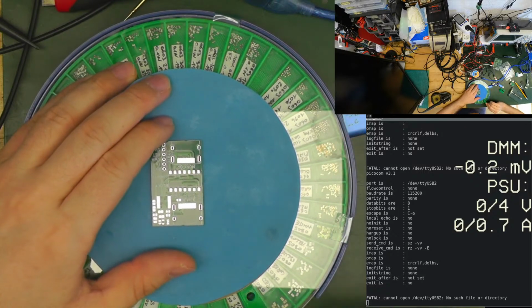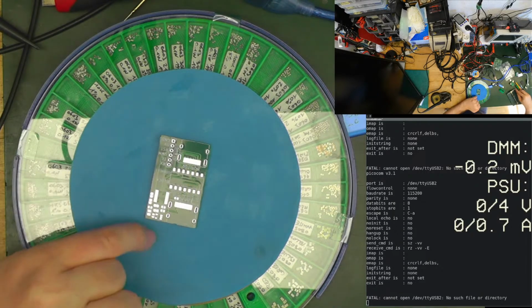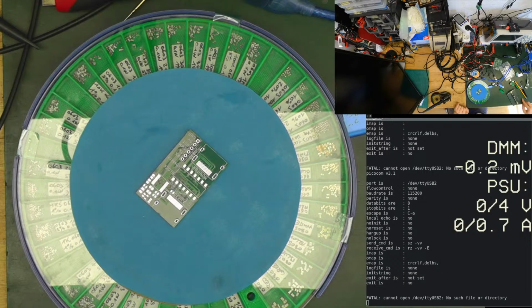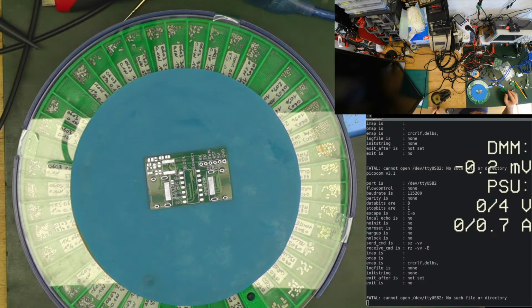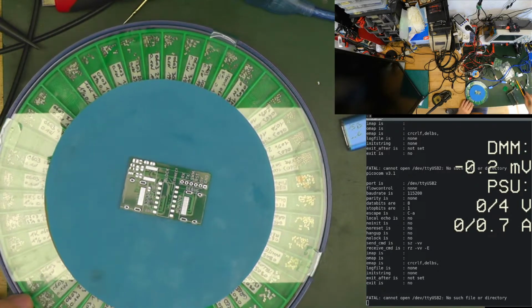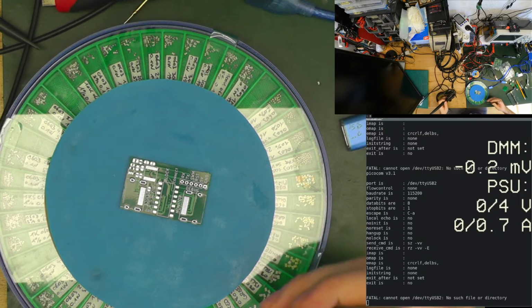Okay, and I will change also the pink LED. And I added, so you probably didn't see it, a footprint for the EEPROM because I wasn't sure that my EEPROM emulation, or that my EDID emulation, was working correctly. It is working correctly, which is fine. Else I would just read and then write in the EEPROM like I do in the previous version. But I didn't need to. I need some fine tweezers. They are here. This is my soldering iron.